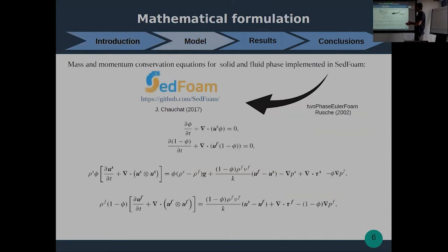So let's put our hands on the mathematical model. To reproduce Eduard's numerical simulations, we're going to use SedFOAM, which is an extension of twoPhaseEulerFoam modified to handle sediment transport applications. So we are solving the mass and momentum equations for the solid and the fluid phase.